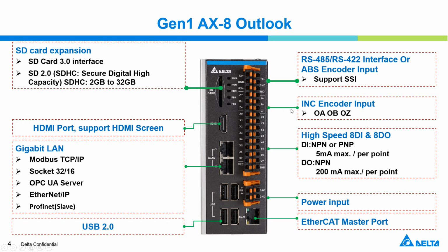Next, it supports the incremental encoder. The built-in I/O is high-speed DI and DO, and you can choose different DIDO modes like NPN or PNP. Here is the power input, and here is the EtherCAT master port.